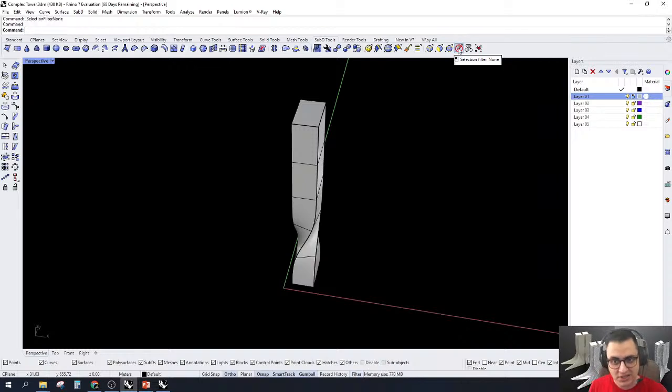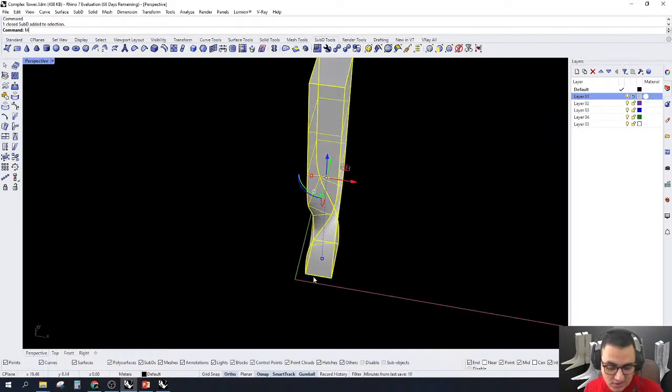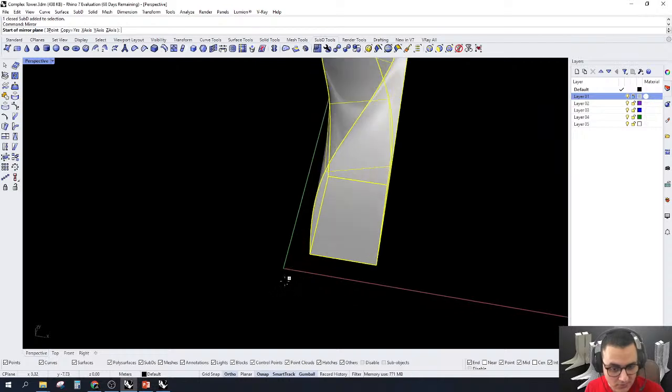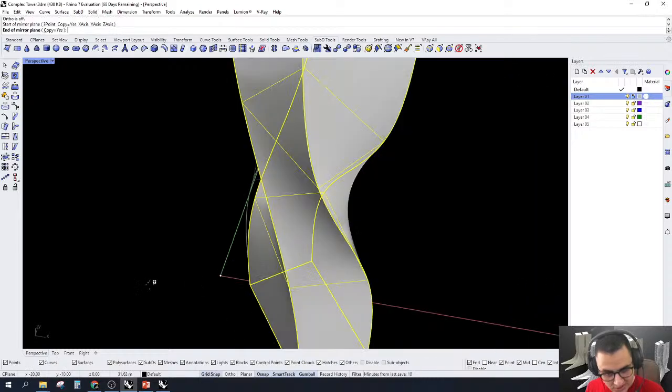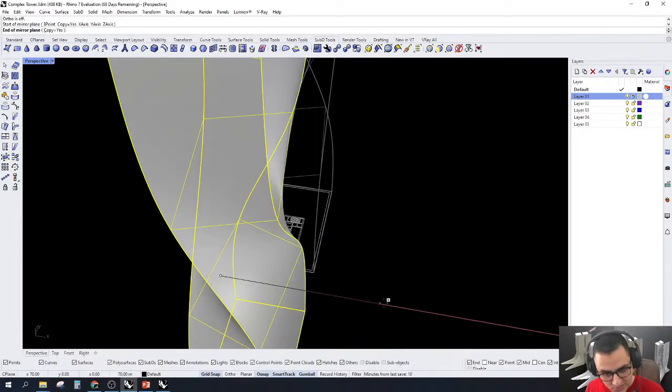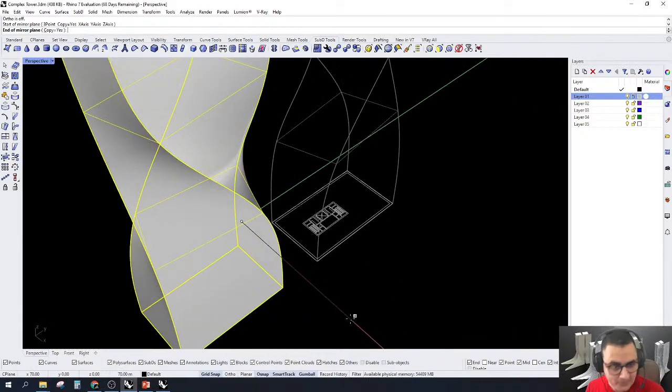Okay, now I will click in here. I don't select any filter of the SubD, and pick the object and simply mirror it, MIR, and hit F8, and the grid, so it will be easy to mirror. Also make sure that you are copying.